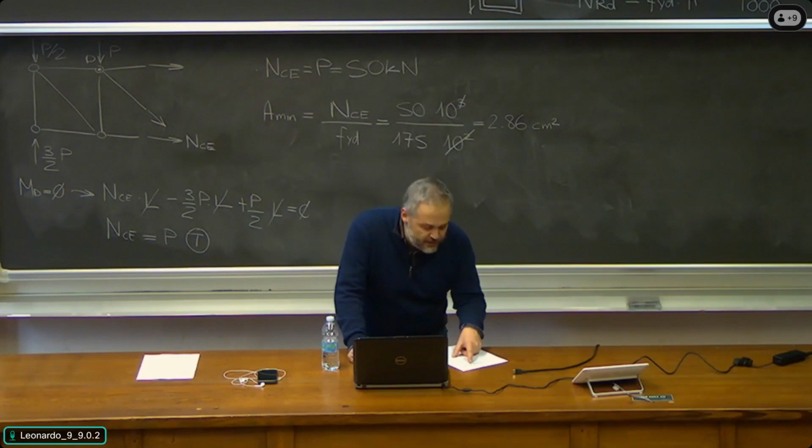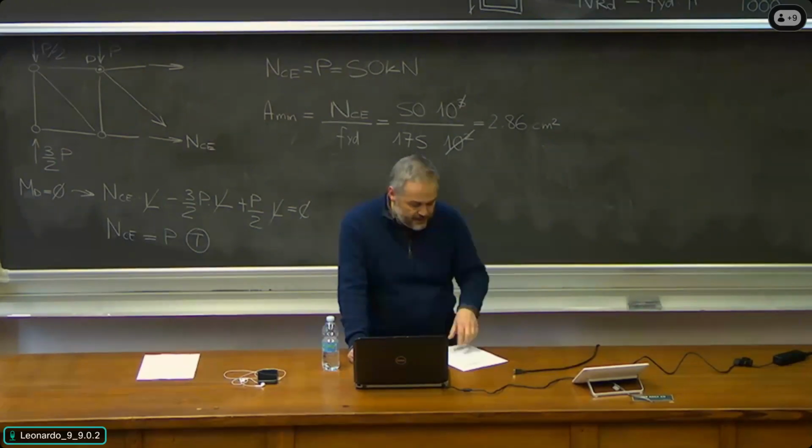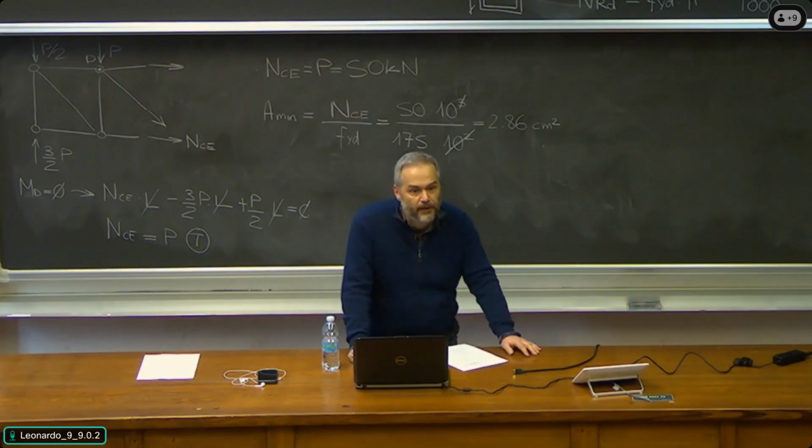But if I move further down, there is a section which is 40 times 2 with 3.04. Now this is a section which, even though deeper and wider, is preferable if the criterion is the minimum weight, because it weighs less. As you can see, 30 times 3 is 2.54. 40 times 2 is 2.39. Why do we choose the criterion of minimum weight?